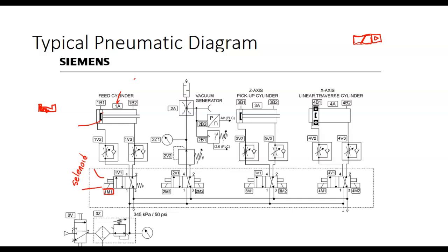So then we move over to circuit number 3. It's got a 4-way two-position valve with double solenoid actuator with manual overrides. It's got two one-way flow control valves that are set up to meter out, right? Then it runs up to a cylinder that's got a magnet on the piston so we can sense it. And that's okay with circuit number 3. Once you learn how to read them, it's pretty simple, right? Once you know these symbols.